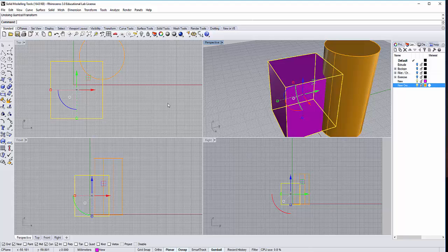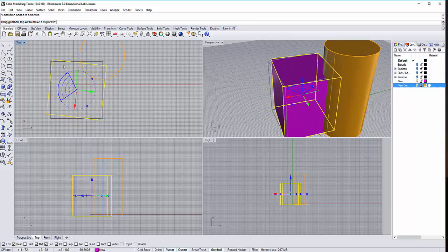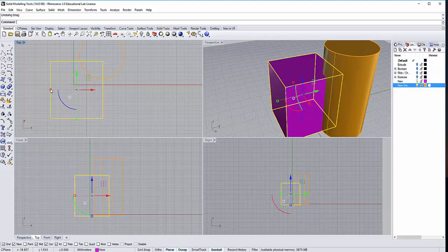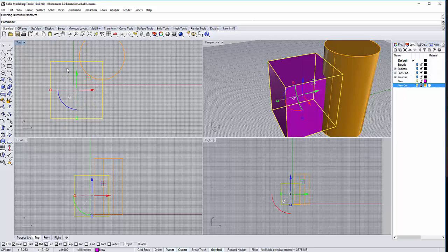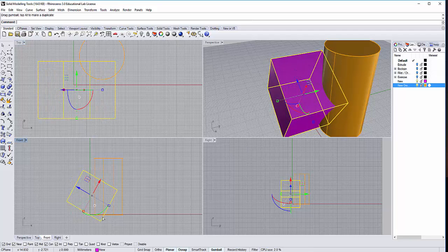Then I will cover rotate. Let's say for example you want to rotate left and right. Just click here. Let me undo. Select again. I can just select and then drag. Undo again. Let me just show you if I want a measurement. Look at the arrow. Where is it pointing to? Right now it is anti-clockwise. I want 30. It will go anti-clockwise. Okay. It works the same way here also. Dragging or inputting numbers.